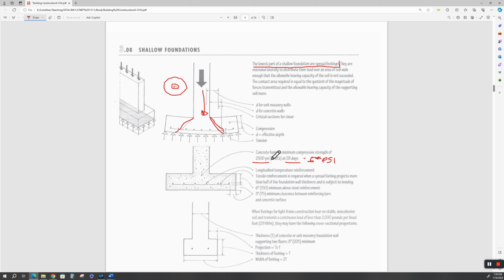This is like freaking Sackcrete that you buy at Home Depot. Okay, your average ready mix is 3,000 to 4,000 psi. That's at about $175 in today's cost per cubic yard. A couple of more sacks of cement in the mix will get you up to 5,000. Anyway, I digress. All right. Okay.